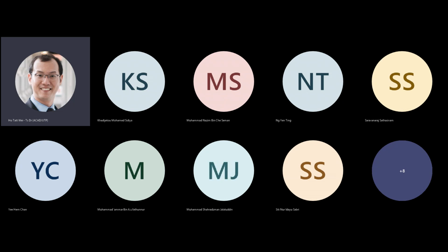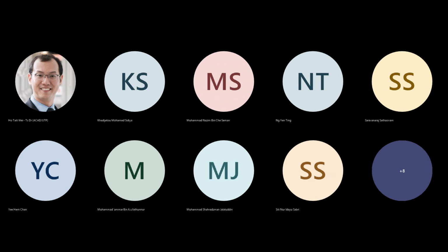The key point for showing you this is because you can see the current is proportional to the dimension of the device. I grow the width of the device, I use a larger device that is growing in this dimension, I will get a larger drive current. And it's inversely proportional to the length of the device. So this is why we like to go to smaller technology nodes, because my digital logic gates would automatically consume less current the smaller I make them.